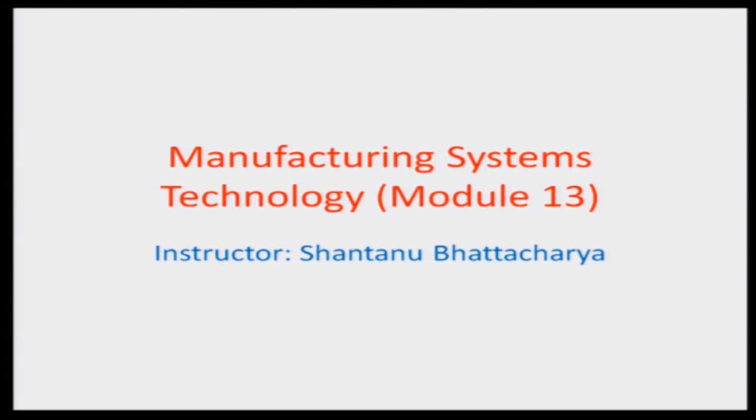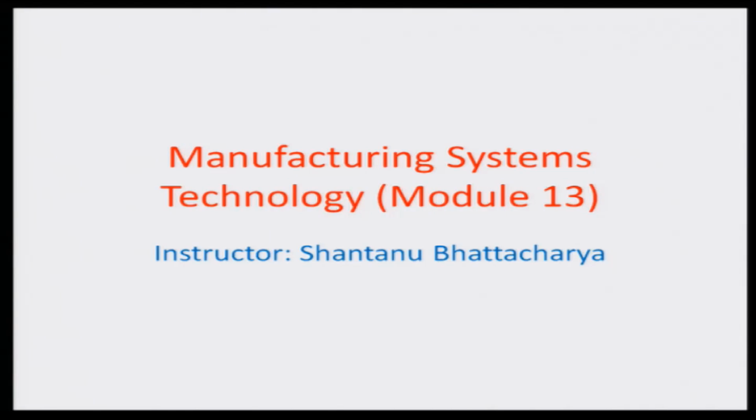Hello and welcome to module 13 of manufacturing systems technology. If you may recall, last module we were discussing the Bezier fit particularly, and we talked about how a characteristic polynomial can be generated, which is also known as the Bernstein polynomial.